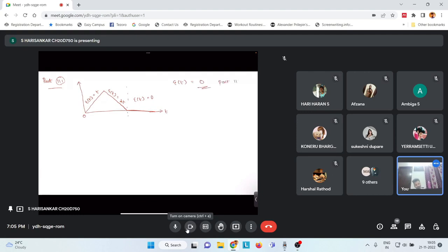So now getting back to our formula, the mean residence time T bar is equal to the integral from 0 to infinity of T E of T dt, and we had divided this into part 1, part 2 and part 3. So this will be the integral from 0 to 1 of T E of T dt for part 1, where E of T is from part 1.